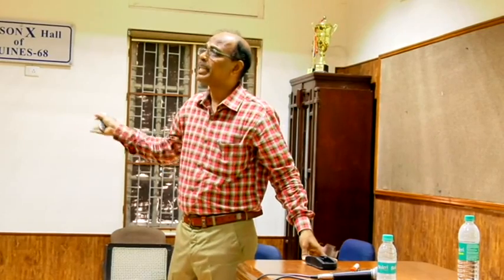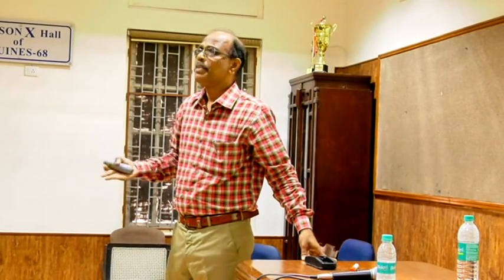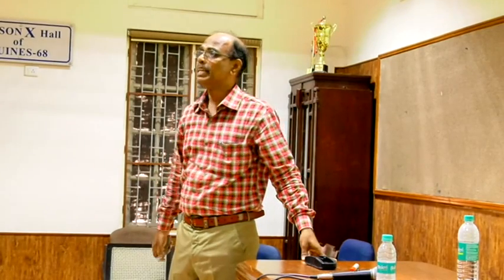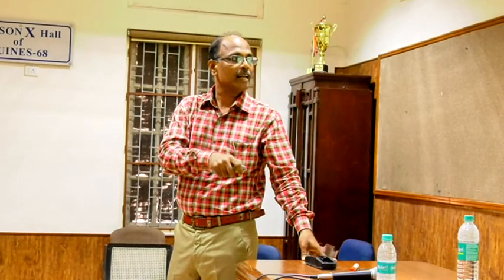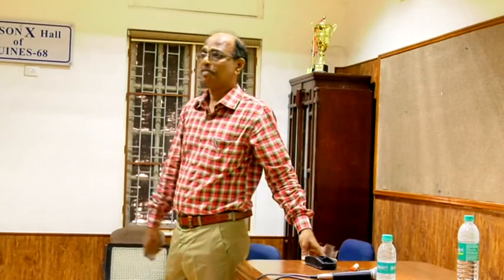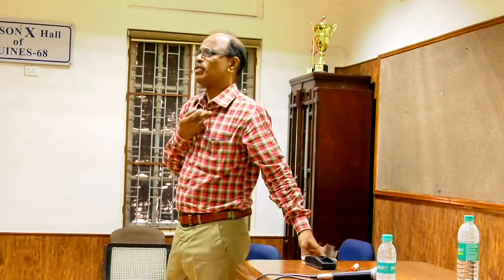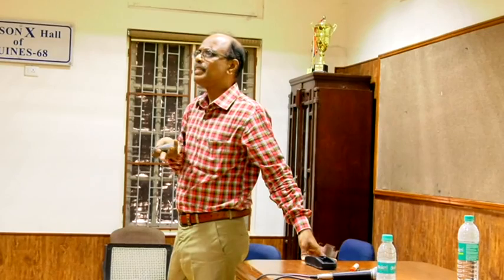Again, Taylor series is a mathematical process. We linearize the nonlinear equation by this process. P of delta comma V naught plus dou P by dou delta into del delta. This way we can linearize the equation. Here we are ignoring the higher order terms. And this can be converted into matrix form. So dou P by dou delta, dou P by dou V, dou Q by dou delta, dou Q by dou V. So the equations we have seen earlier can be partially differentiated with respect to variables, and we can form the Jacobian matrix. The Jacobian is very popular in almost all engineering fields. Not only engineering, even statistics problems use the Jacobian.